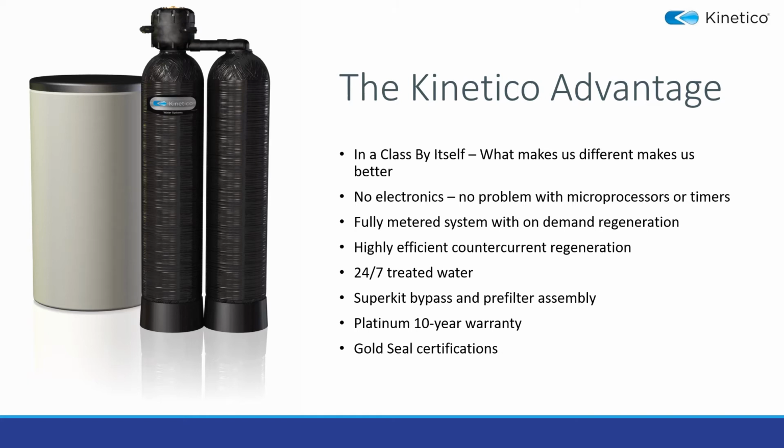Single-tank electronic softeners do not offer this same level of engineering. First, the unit will regenerate based off a timer. The downside to this process is that the unit does not measure the usage and results in the regeneration prematurely or not enough. In addition, these units will use hard water for the regeneration process. This is counterproductive as the system is using hard water to remove hardness, which potentially results in more water and salt usage, but does not effectively regenerate the resin bed, leaving residual hardness.